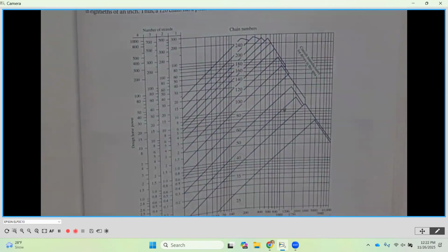And those you're going to take into consideration when you're in machine design problems or machine design elements, where now you're going to be considering what is the input power, what is the output machine that you're going to be going to, and maybe some other things about the speed, and then also the life. But for the most part, design horsepower and horsepower in our problems are going to be the same.